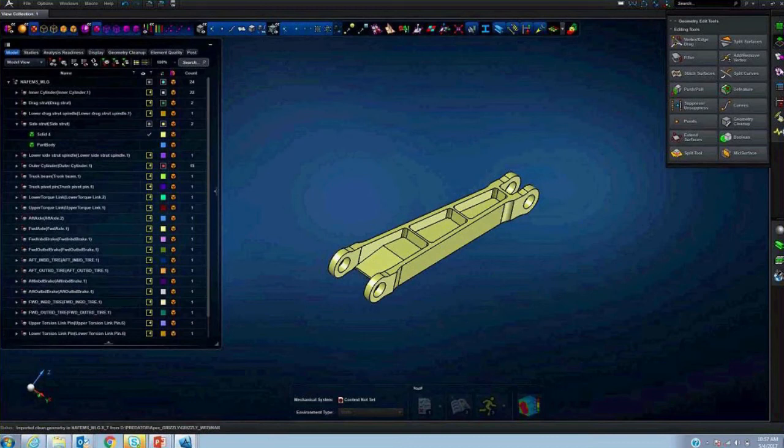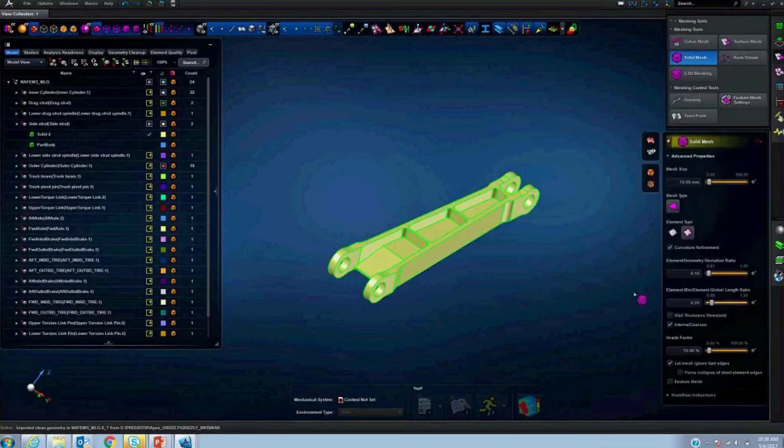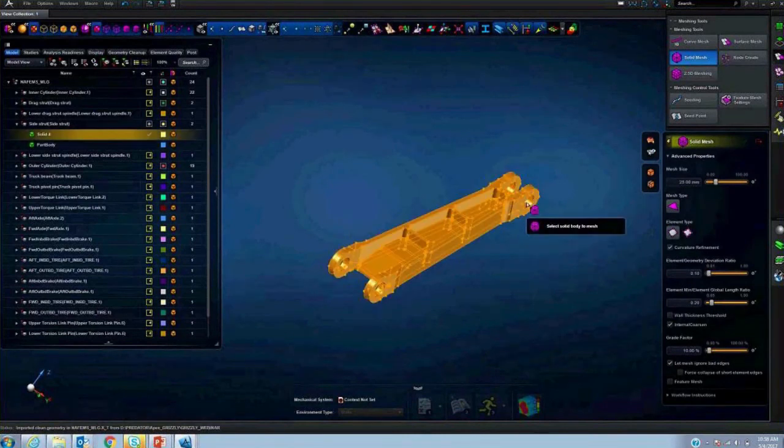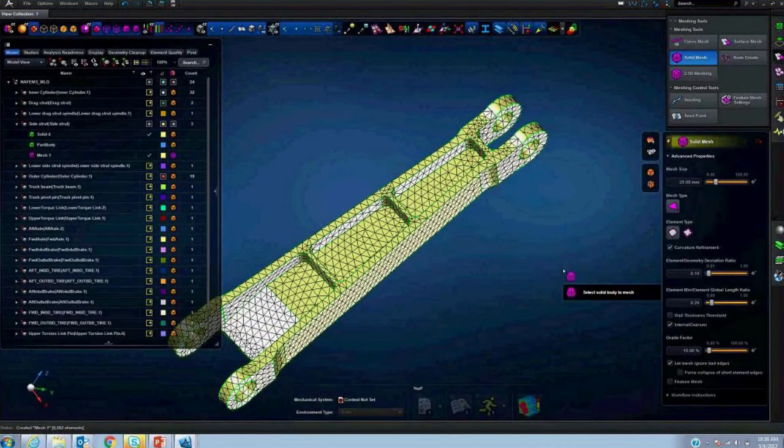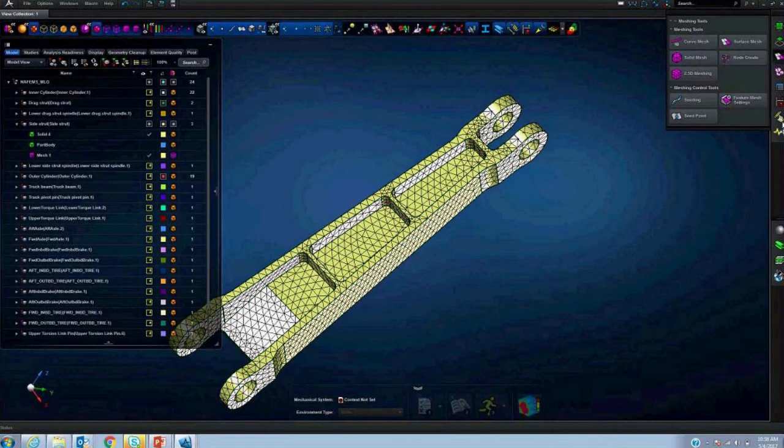And quickly, we can go and mesh this part. Let's make it maybe 25 millimeter element size, and hit mesh. Meshing is done. Now we need to define what is called the interface point, where we are going to reduce the math representation of this model as a model neutral file so that we can take that into the world of Adams. And how do we do that?